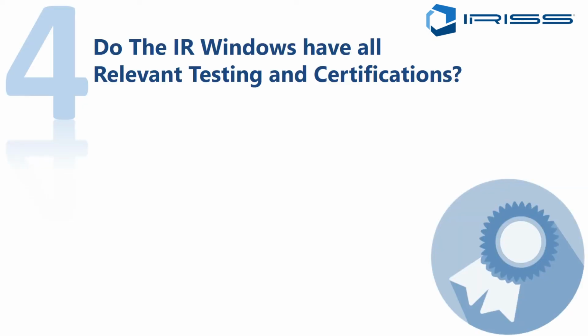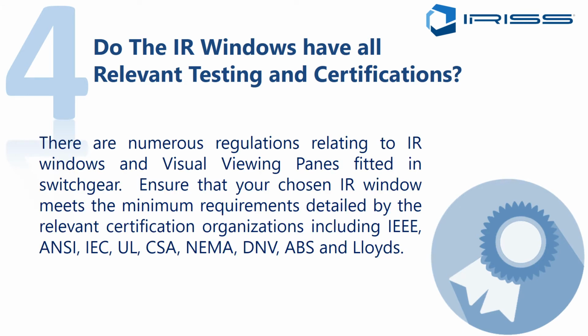Do all the windows have all the relevant testing certifications? Now, there's a whole myriad of test requirements for infrared windows or visual view, and we tend to test our infrared windows to the same standards as visual viewing panes because they've been there for a long time. So you've got standards from IEEE, ANSI, IEC, UL, CSA, NEMA, etc. I mean, you can go on and on and on.